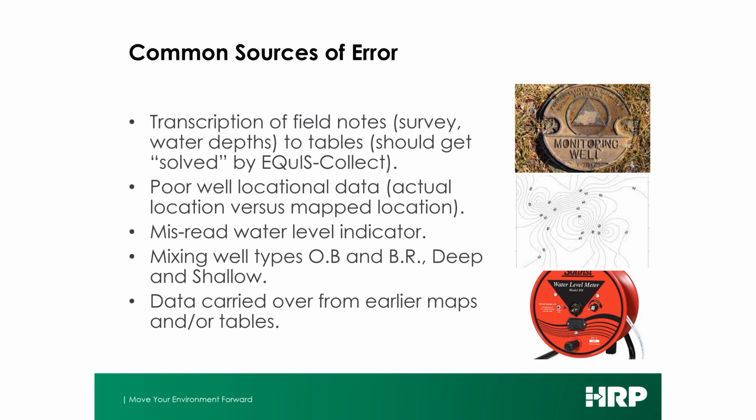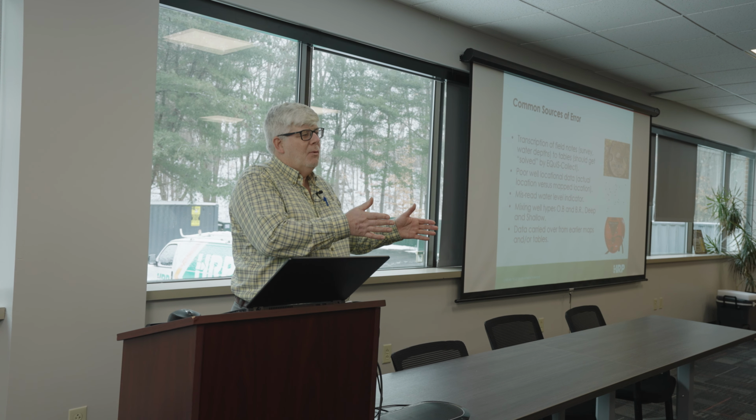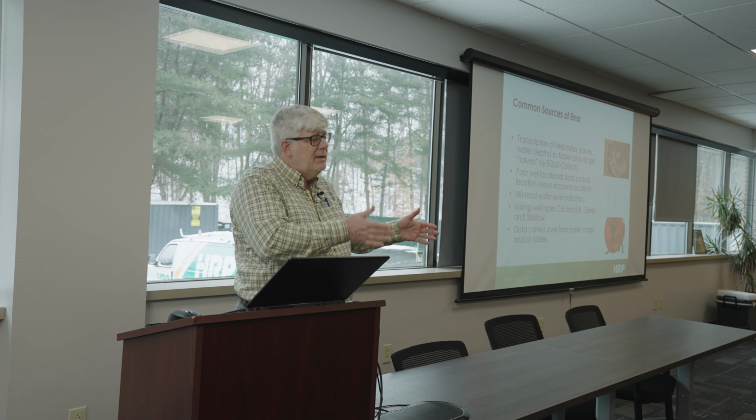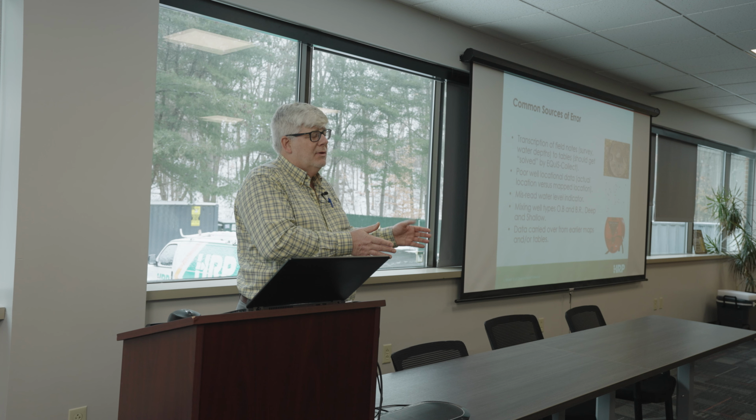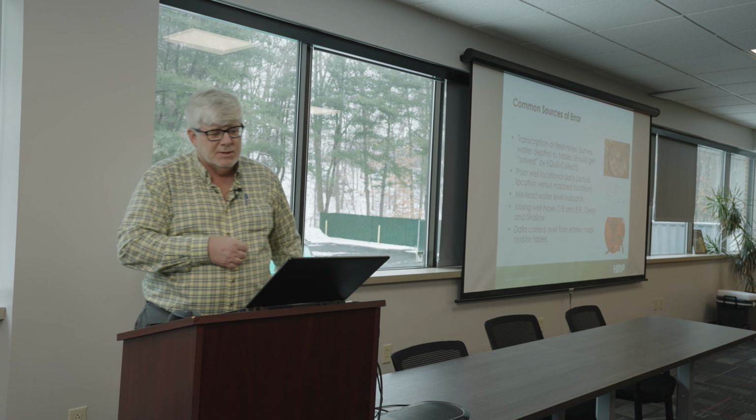One thing we run into from time to time is people aren't taking the time, or we're working with maps that somebody else made where the wells really aren't where they say they are on the map. Always something to check, particularly when you're out there. The map makes it look like it's about 5 feet off the building and it's 25. That can move that whole point over. And on a flat water table area, that can be really significant in your interpretation of the water flow. So, things to pay attention to.